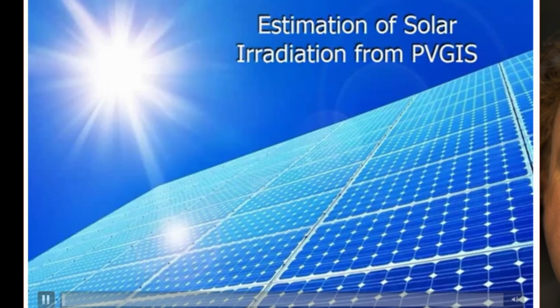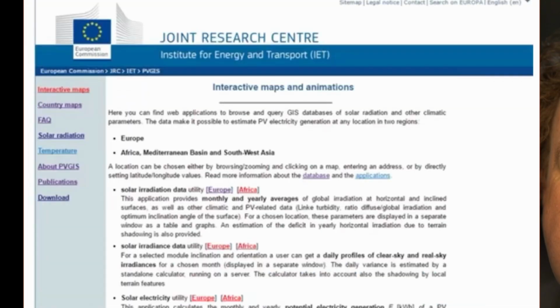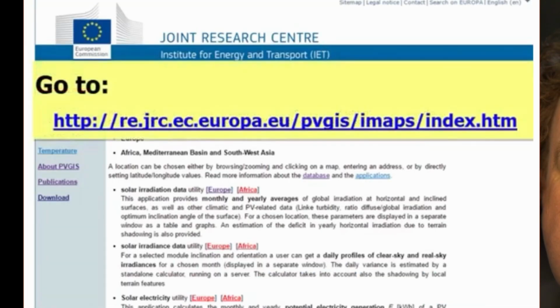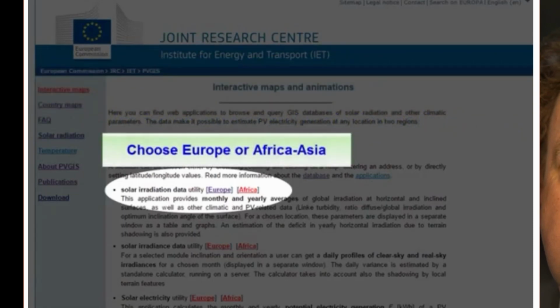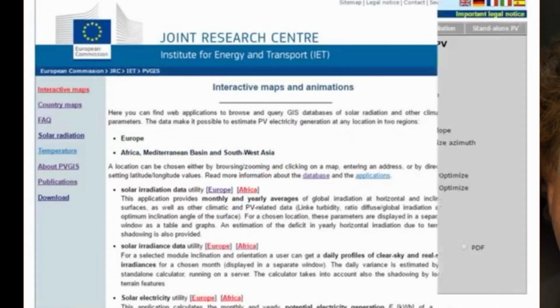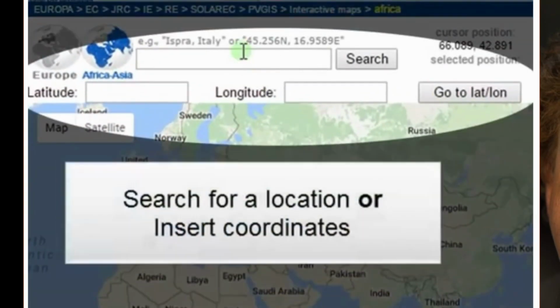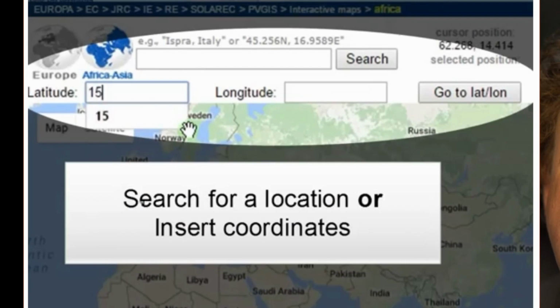In this video I will show you how to estimate solar irradiation using PVGIS database. First, go to PVGIS website and click either Europe, or Africa for Africa and Asia. We will choose Africa and Asia. You can either search for a location or key in latitude and longitude. We will key in a location in Middle East with 15-degree latitude and 45 longitude.